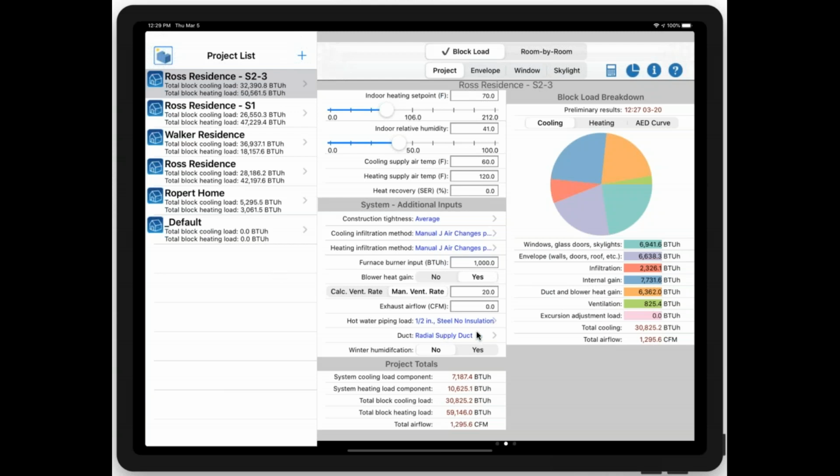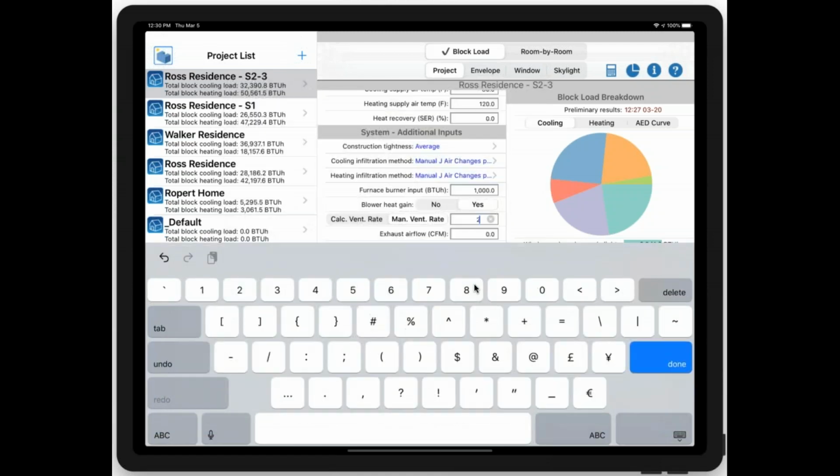Or some small value maybe for the loss of the 10%. A small value for what? For the loss of heat for the 10% recovery. In other words, 90% recovery, so you're losing some heat. So maybe you put a small CFM value in there, like 10%. Yeah, maybe a little bit. You may want to put a little safety factor in there, so maybe like 10% of the value of the air being exchanged.